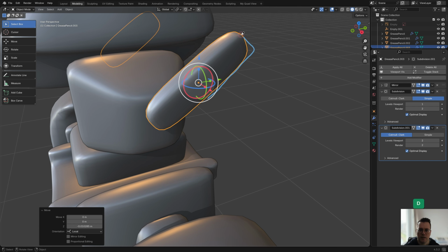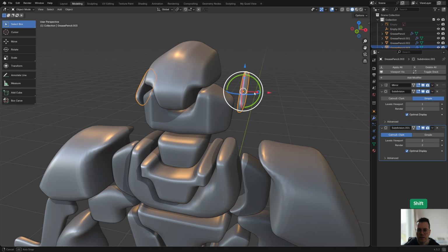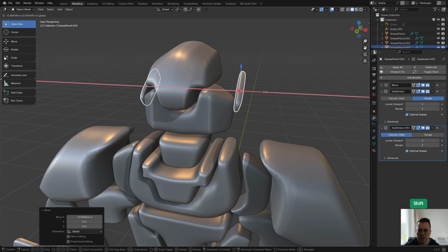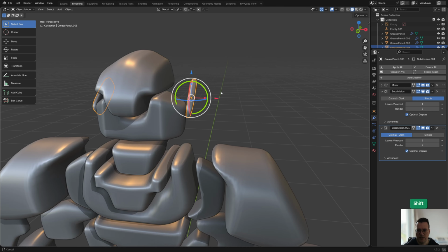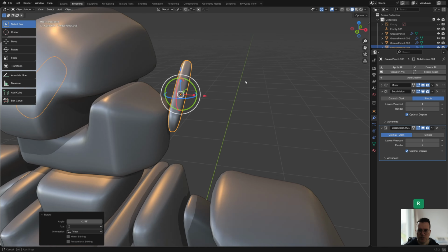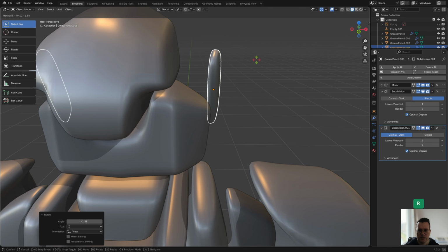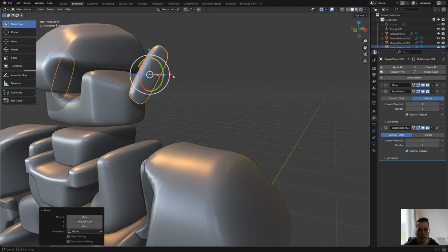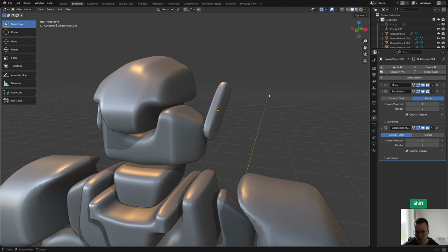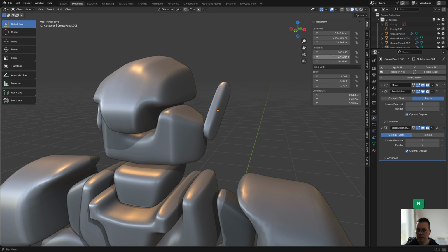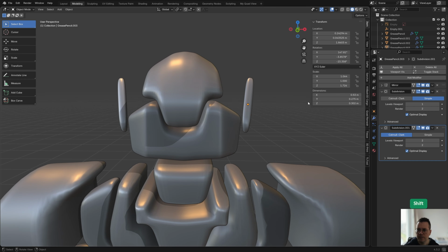And then I can just quickly erase this annotation. And maybe we can move this a bit closer here. So it becomes kind of an antenna or something. And if you just want to be able to freely rotate something, you can just press R twice. Then you can just kind of rotate it like this. And by the way, you can also find those rotation values. If you press N here, then you will get the option panel. And then as you can see here, there's also these rotation values. And I would recommend holding Shift. Otherwise it will go very fast. So with holding Shift, you kind of have a more subtle control over those values. And also the scale and location values are here.